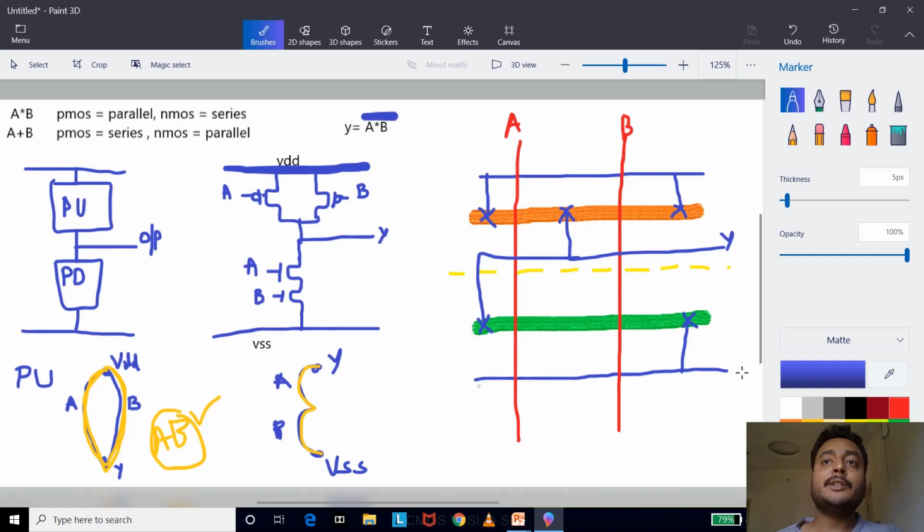So this is how you can write it. When you are writing a stick diagram, make sure that no other endings or interconnections are left behind. You can think of these two terminals as two hands. A is one person, B is one person. These two persons hold one hand together, and the other hand is free. No hand should be free once you complete your stick diagram. Otherwise, that means you're leaving some connections. Make sure that no terminal is open.